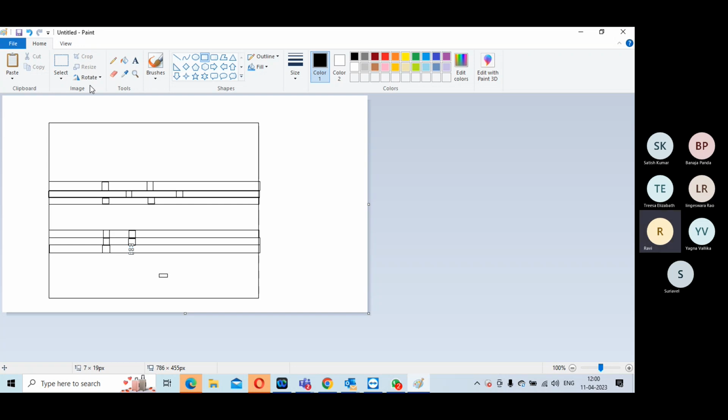I'll create a spare group, let's say a spare group of 1. In that spare group, I'll add one NOT cell. Every spare group should have at least one inverter so that any logic can be constructed, and minimum basic gates, an AND gate. With an inverter you can create NOR, you can create NAND, whatever it is. So one NAND gate and one NOT gate, and then you can have some NOR, some 3-4 types.